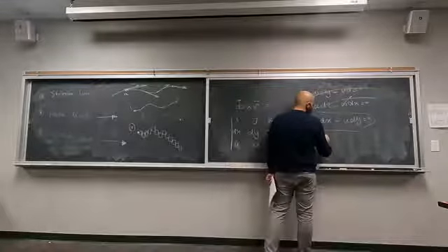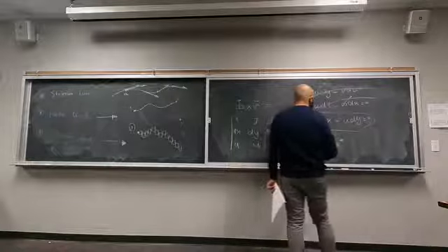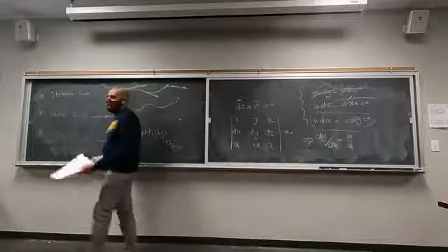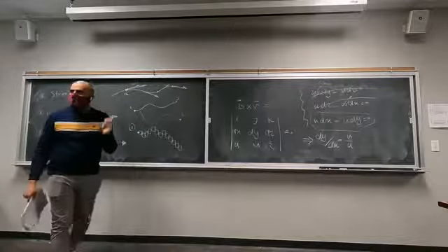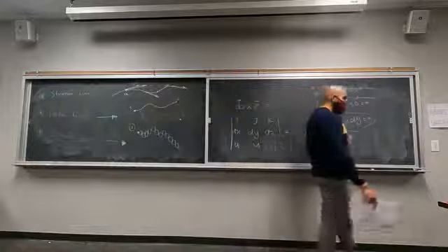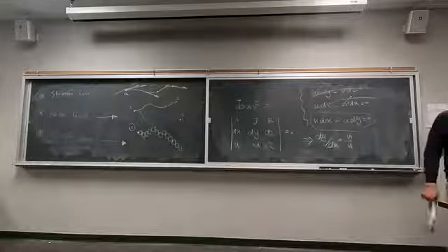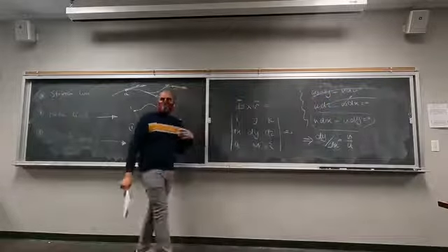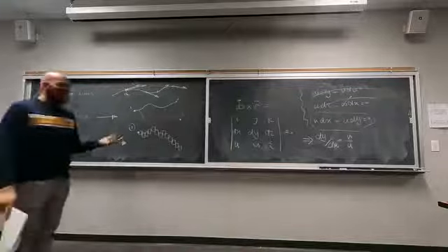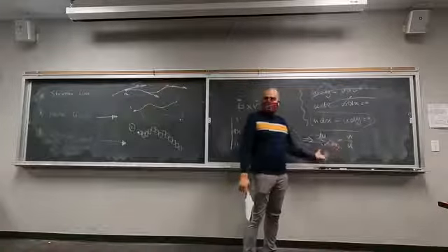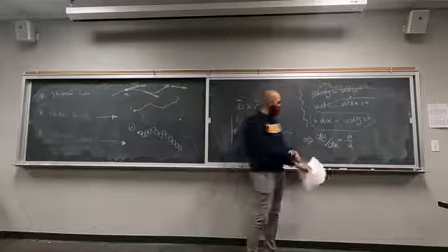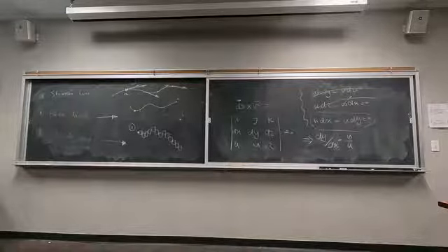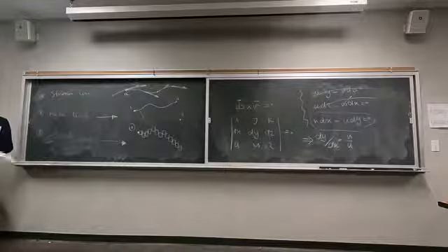If you rearrange this, you're going to get dy over dx equals v divided by u. What does this mean? This essentially means that we can find the slope of a streamline by having the velocity component at each point, which means you can find the equation of that line by having this velocity component. This is the slope of the streamline, right? We understand that, hopefully. dy/dx is the slope of this streamline. So by having the velocity component in each direction, we should be able to find the equation. Are there any questions so far?